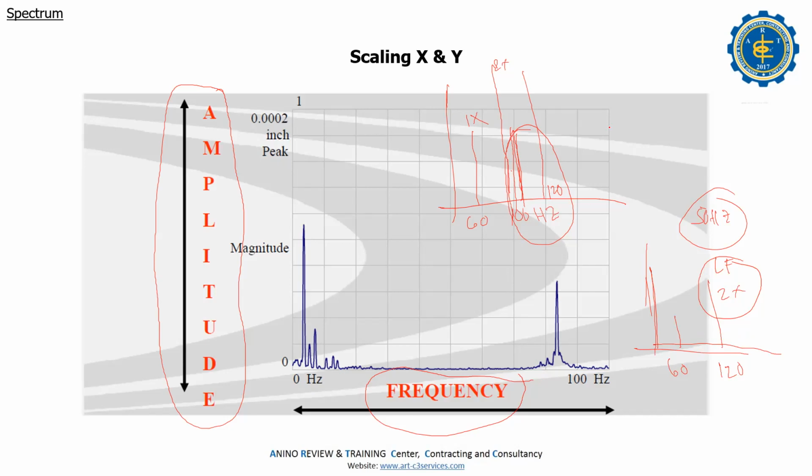So, sir, you said in Filipino that line frequency is 2x. Obviously, if it is at 100 hertz, then there is a problem, electrical issues. That's why here in the Philippines, mechanical and electrical technicians quarrel because they are pointing at each other, electrical problem, mechanical problem. Not like if your frequency is 50 hertz, then you have 100 hertz here, and you say there is an electrical problem, right?